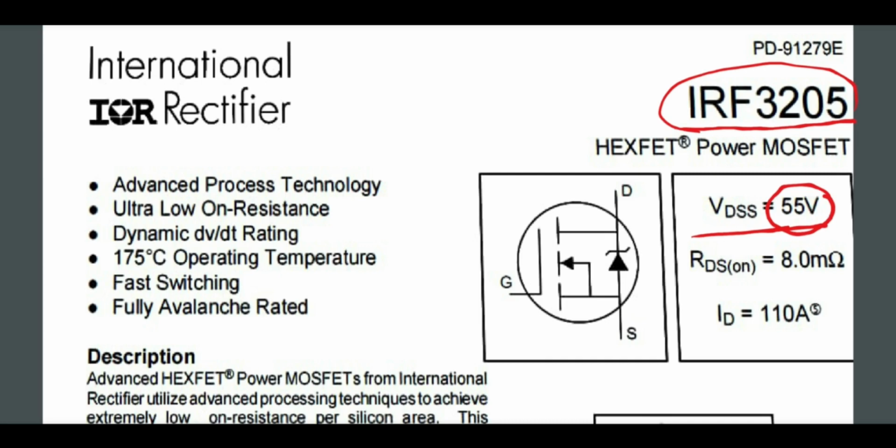So in the case we were discussing, when the gate voltage went from high to low, what happened to the drain voltage? The drain voltage rose to some unexpected level, or we could see a spike in the drain voltage.